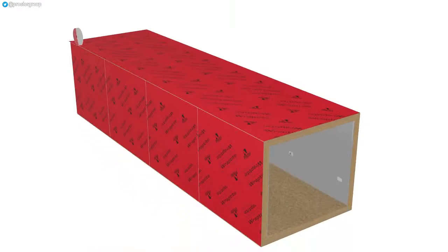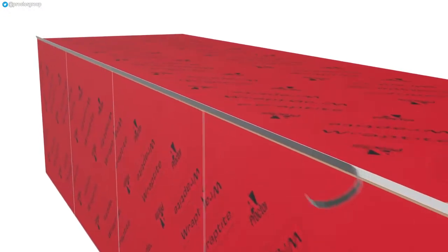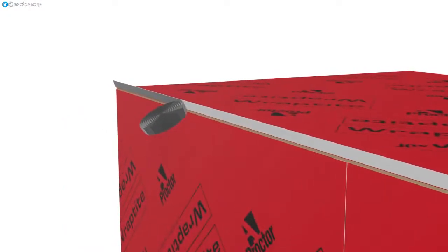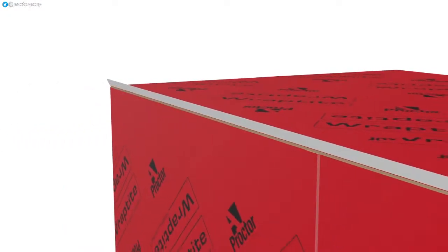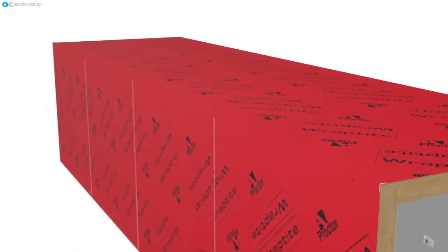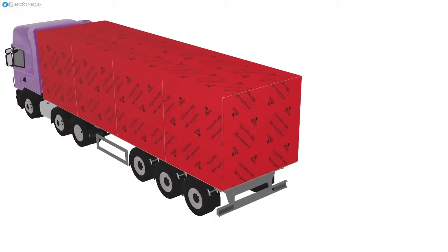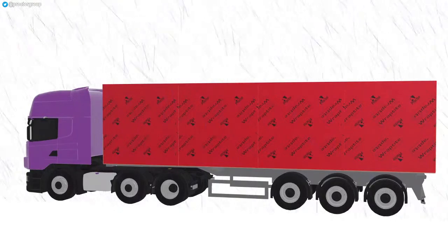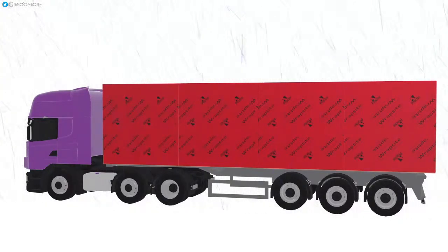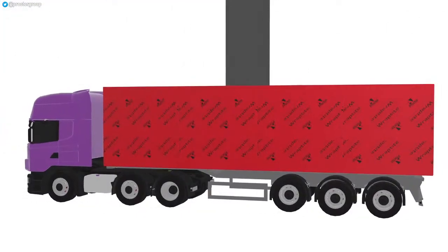These wall, roof and floor panels can then be assembled into modules, and the wrap-tight split liner tape used to complete the airtight seal between adjacent assemblies. This tape simplifies making such joints by splitting the release liner in half, allowing the two surfaces to be stuck independently, making the joint faster and more accurate. These completed modules can then be transported to site. During transportation, the self-adhered membrane ensures watertightness, protecting internal components and minimising on-site remediation work. The building can then be assembled on site and completed as normal.